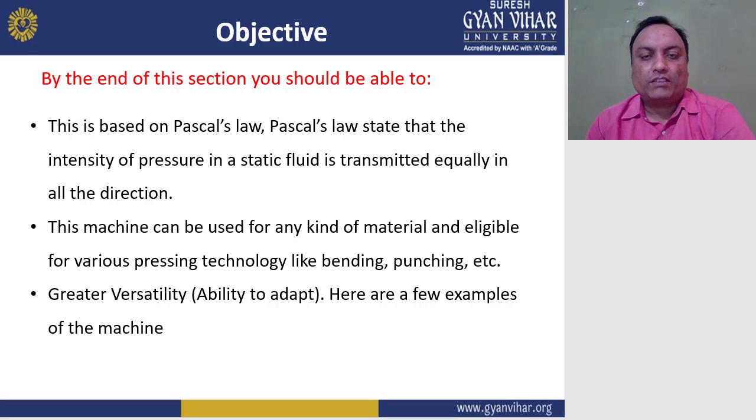Pascal's law states that the intensity of pressure in a static fluid is transmitted equally in all directions. This machine can be used for any kind of material and is suitable for various pressing technologies like bending, forging, and others, with greater versatility.